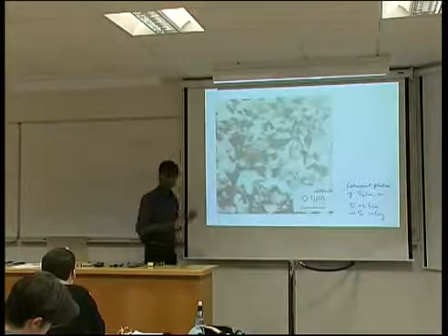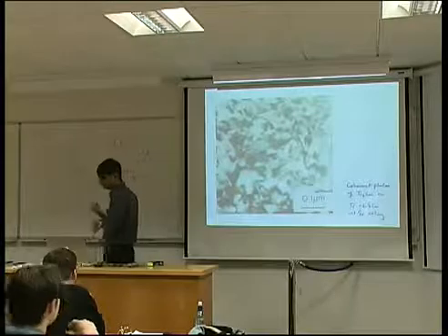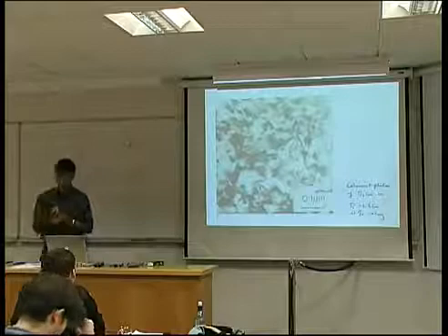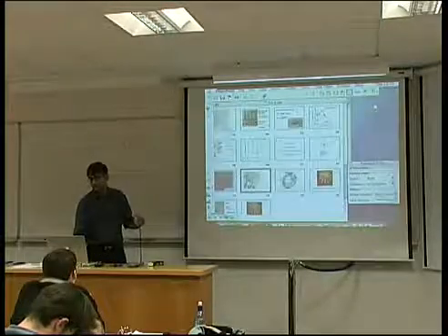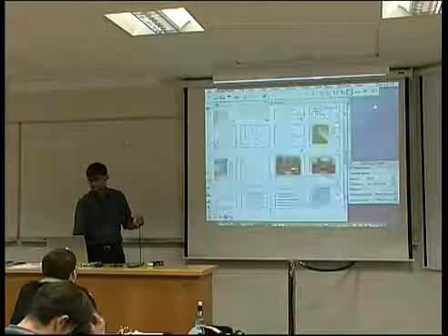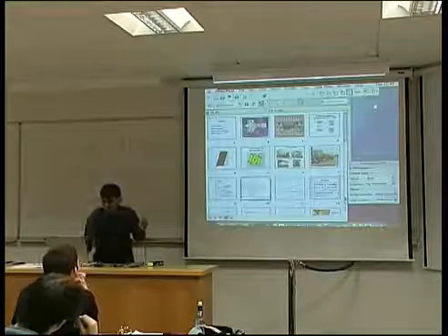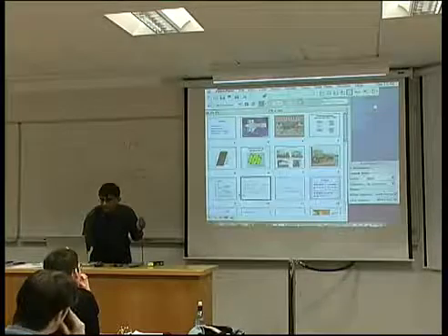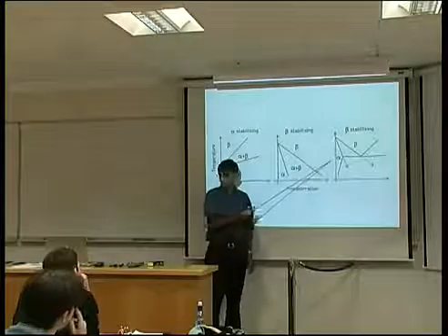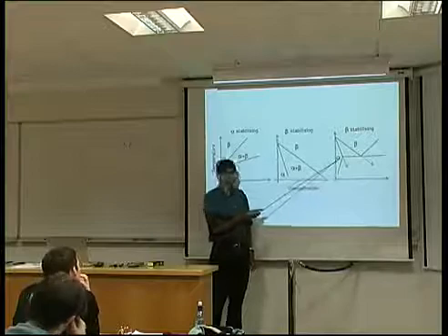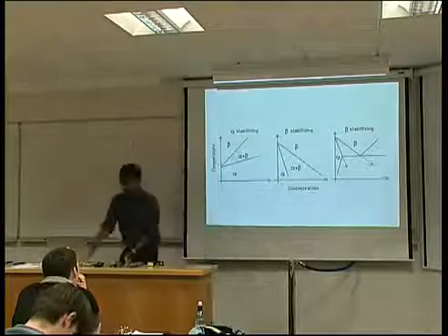Okay, to finish off, there is an important class of alloys which are precipitation hardened alloys. So obviously, if you have a phase diagram which shows this kind of miscibility, solubility change, then you can age harden it by heat treating here, quenching, and allowing precipitation to happen.